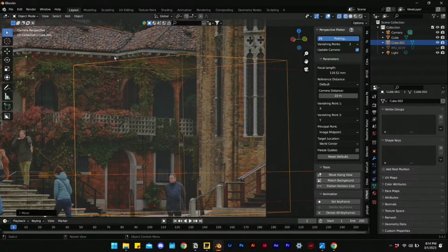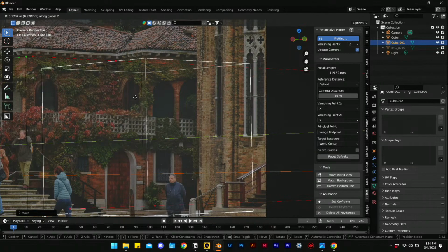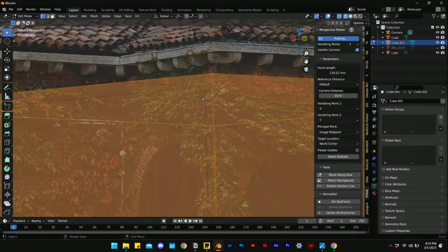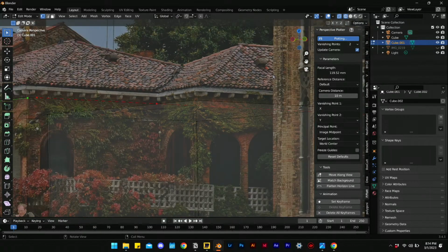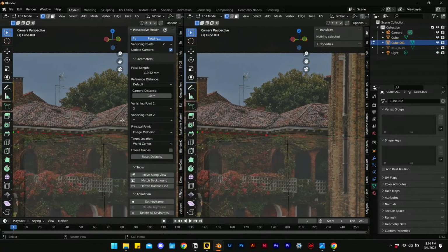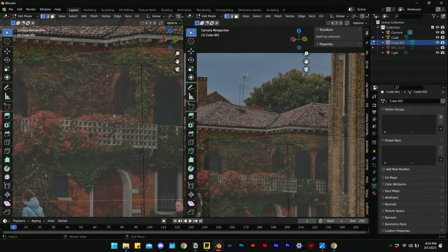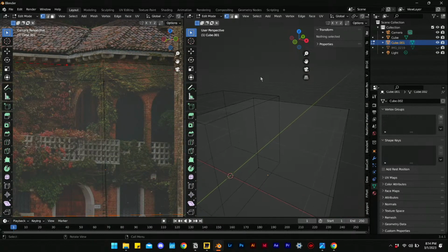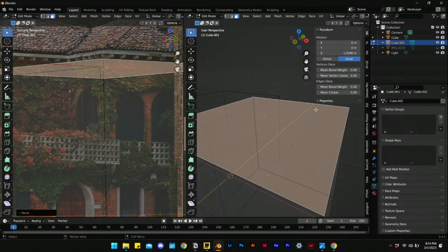Oh, you're right, because we have this little inside corner. So I just have to bring this cube over this way and just line up that corner right there. I can tab into it and I can select this top surface. This is where having our 2 views, as usual, helps. We can see the camera perspective there, and we can see the 3D scene here. And go into face mode, select this one here, and just move it up to meet right there.